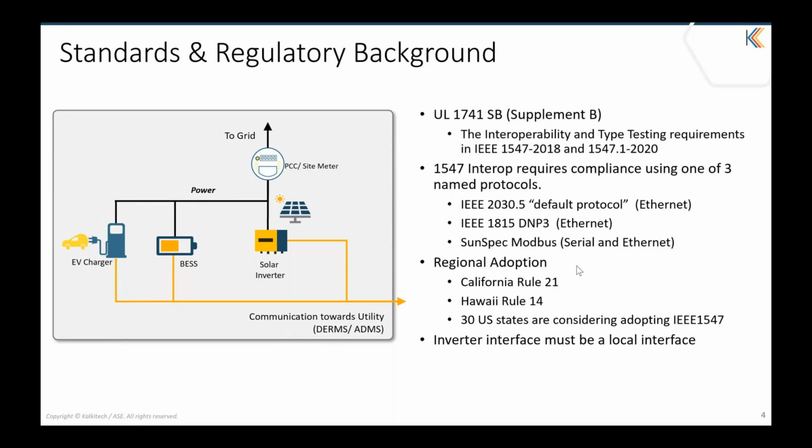These functions include voltage regulation, frequency regulation, power factor correction, and more. UL 1741 is important because it helps ensure that these inverters or converters operate safely and reliably, and do not interfere with the operation of the electrical grid.